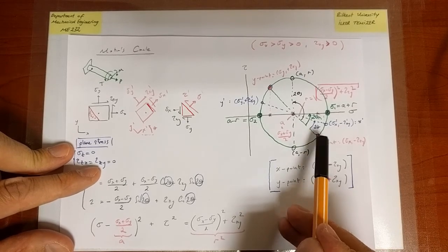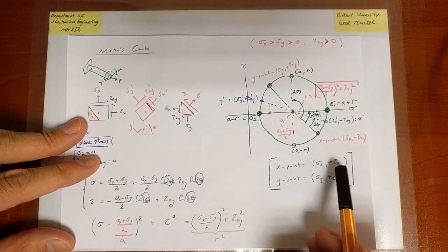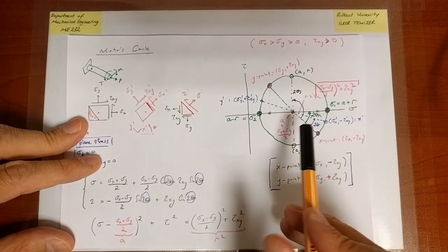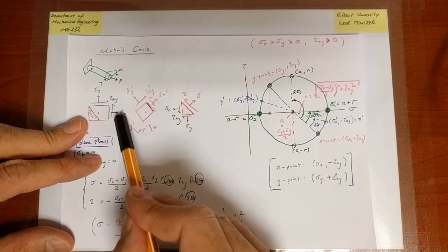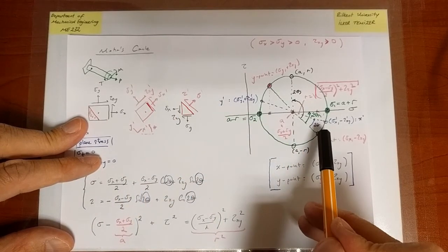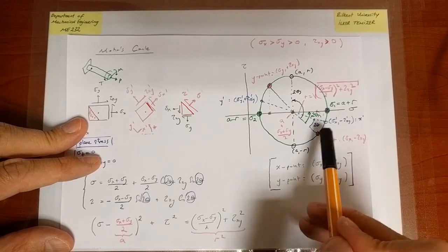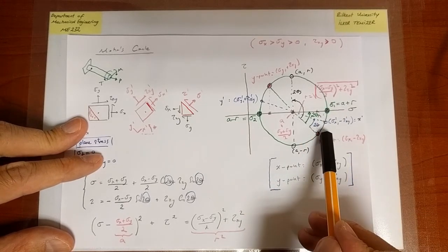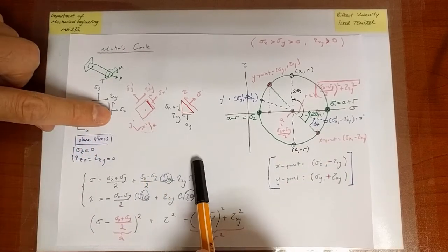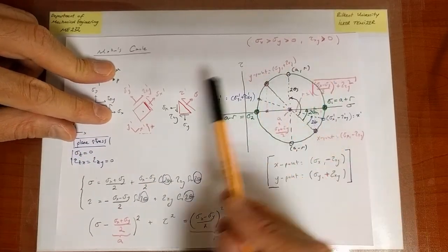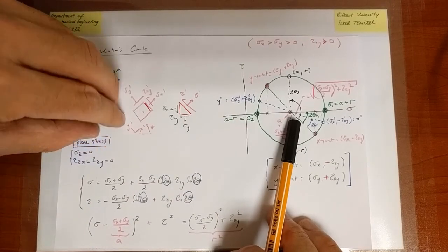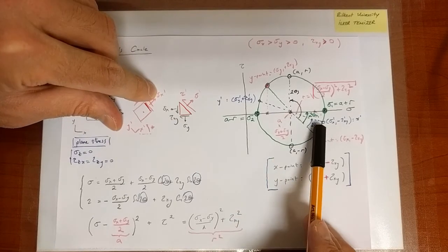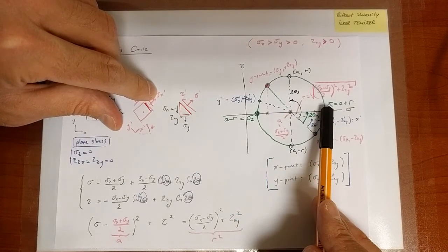And finally, there's one more thing we want to now comment on. Why did we put a minus sign there? Now here you see I am rotating in the clockwise direction, and if I do everything like this, if I rotate also in the clockwise direction, I reach a plane with maximum normal stress, which is associated with the rotation of x. In other words, if I have a picture that is consistent with these assumptions, if I rotate in the clockwise direction, I expect sigma x to increase and sigma x prime increases further towards sigma 1, right?